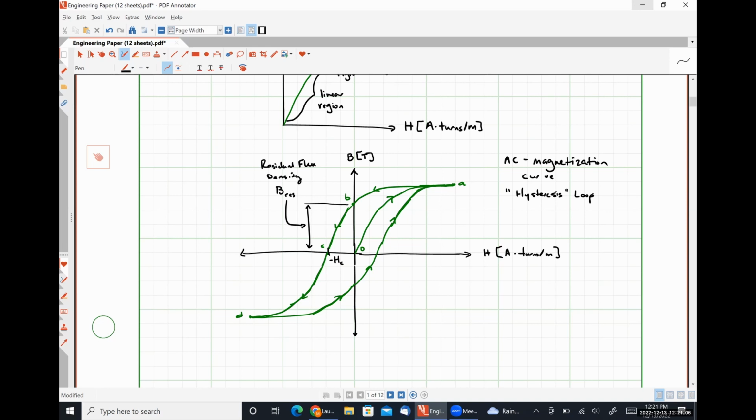This is literally how old magnetic storage material like floppy disks and magnetic tapes, like those used in cassette tapes, VCRs, 8-tracks, and all that kind of stuff, work. You magnetize them to some certain amount in some certain region, and that is considered an on state. If it's not magnetized, it's an off state, and that's how you get your binary ones and zeros that were interpreted by computers. Now we use effectively the states of transistors and all that kind of stuff to do the same thing, but back in the day, it was all magnets, okay? Which is why you can't store any of your old magnetic media in the presence of permanent magnets, or it will erase everything because it turns everything to ones or everything to zeros and corrupts your data, okay?